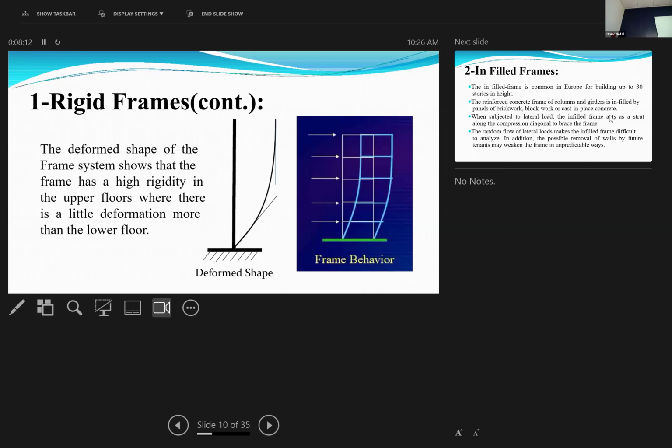But look at the slope of the building. The slope of the building is very, very steep at the lower floors. But when it comes to the upper floors, it's going to get less steep because the curve of the building is that way. So the slope at the support is much higher, but here it gets better. The less the slope, the better the system. Why? Because when we design these columns, the column in story number 1 here and story number 2 here, that means that there's a bending moment on this column that way. The more the deformation, the more the bending moment.